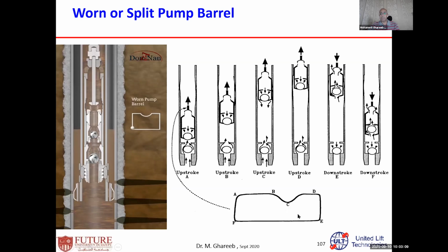But in this case, you do not find some problem in the downstroke, because in the downstroke, all the fluid load is on the standing valve. It will be applied on the standing valve in the tubing itself. And this is the animation of this one.